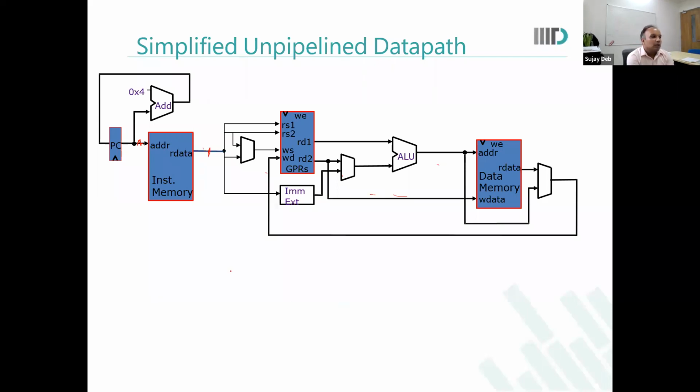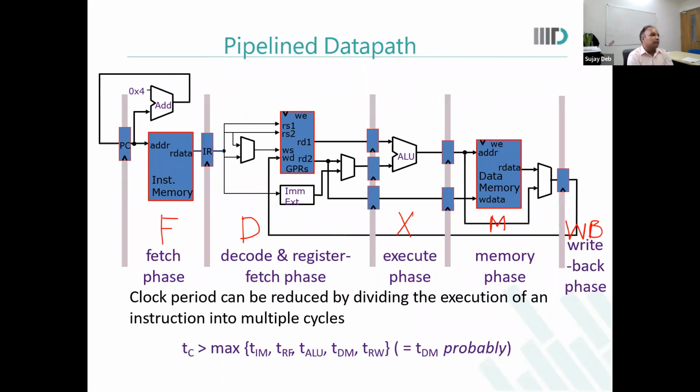Without that, you can only deal with one instruction at a time. So basically, you fetch one instruction, you go through all 5 stages, and once you are done, only then do you allow the next instruction to be fetched, because otherwise there is nothing controlling this flow. So to control this flow, we have to have these sequencing elements, which are nothing but flip-flops.